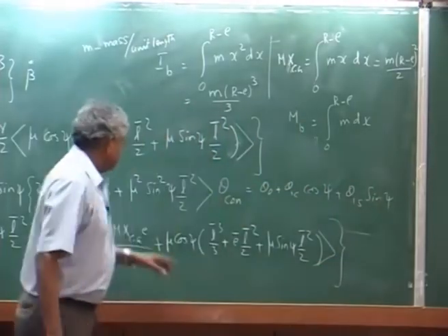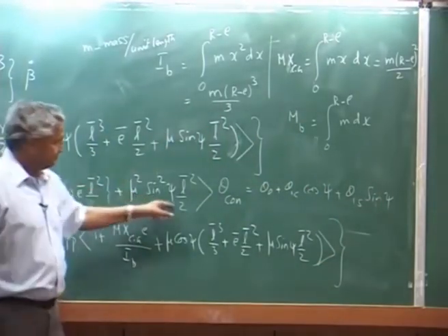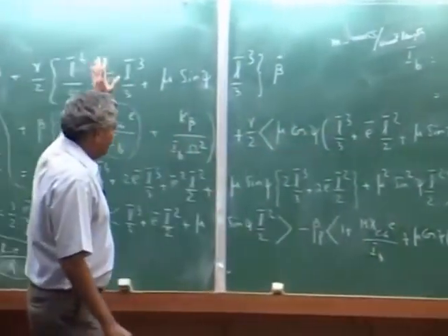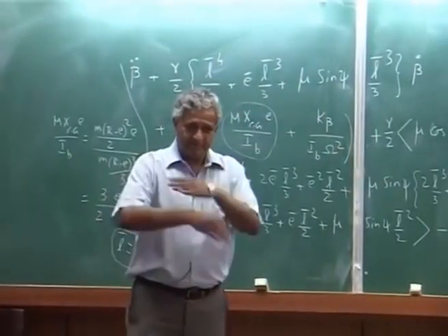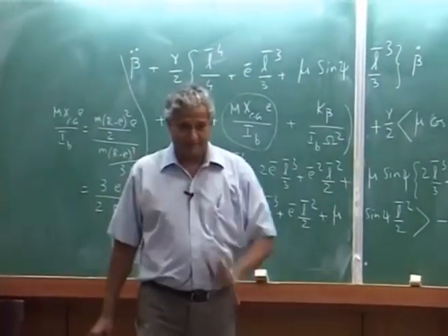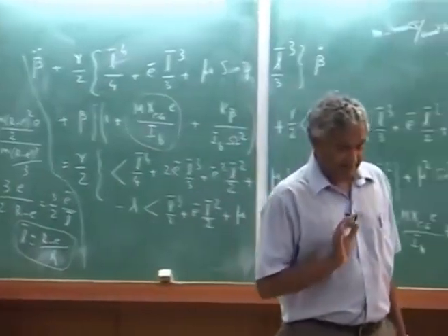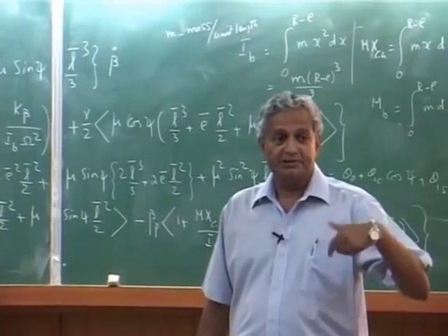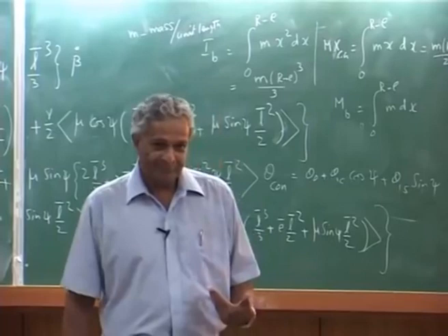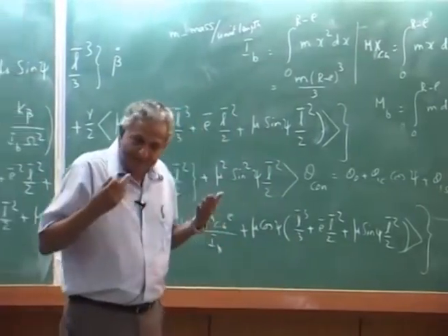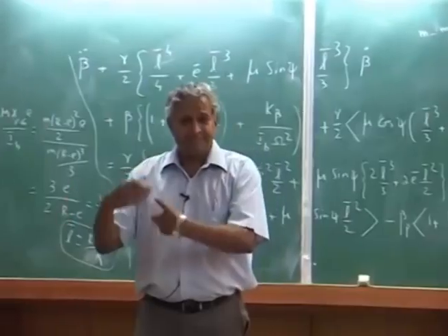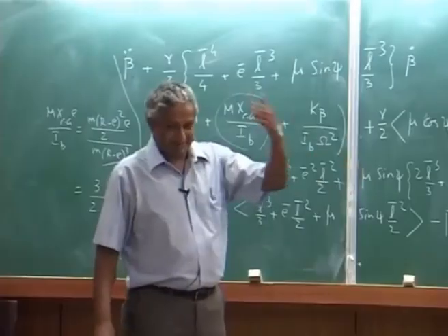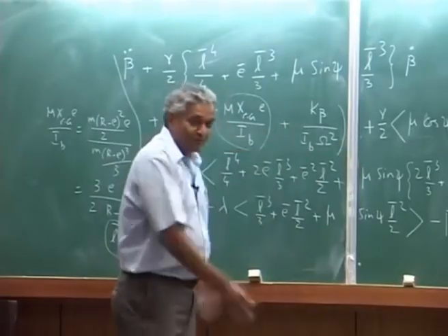You have already second harmonic, this gets multiplied, third harmonic, all the harmonics can come. So, I neglect everything and take only first harmonic, but that is not correct, because as you go to high speed, you will find slowly second harmonic will dominate over the first harmonic. But this is the assumption we make, and our results will be wrong, but it is okay, I am getting some trend. Otherwise you have to take the full thing.